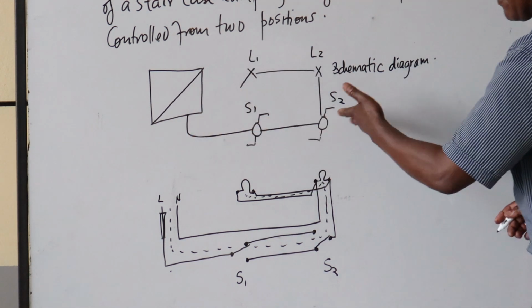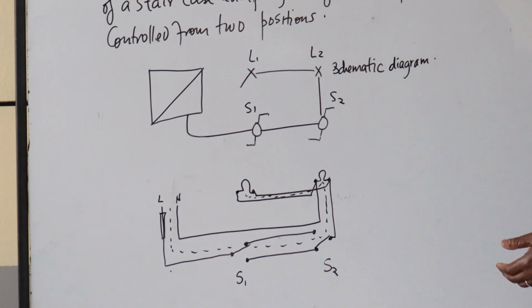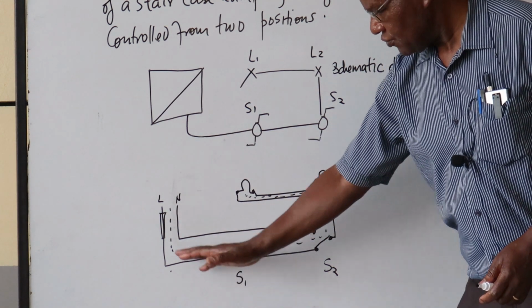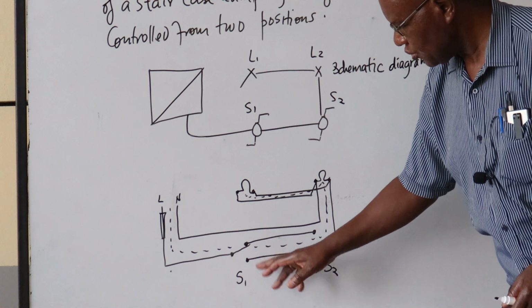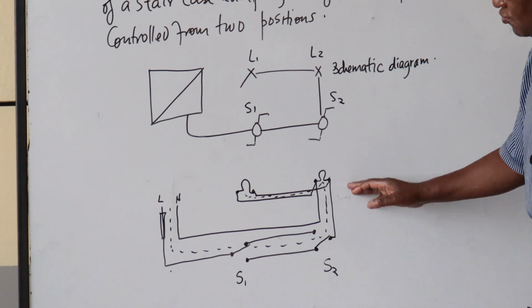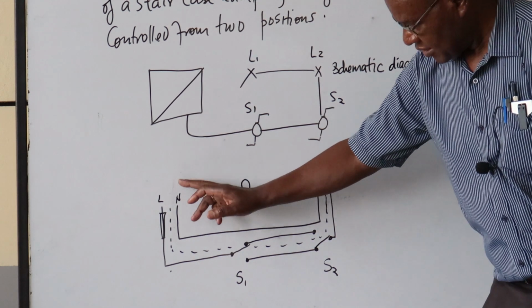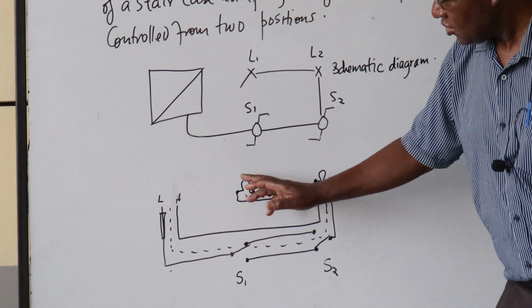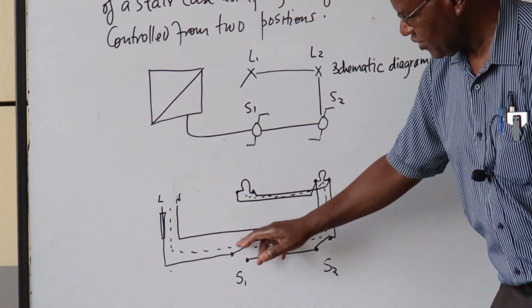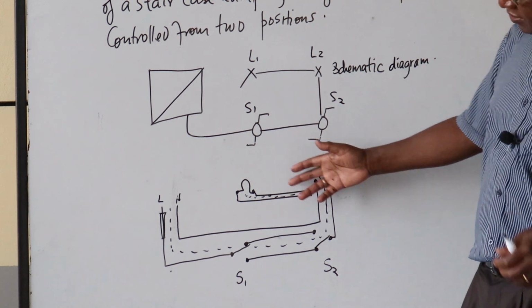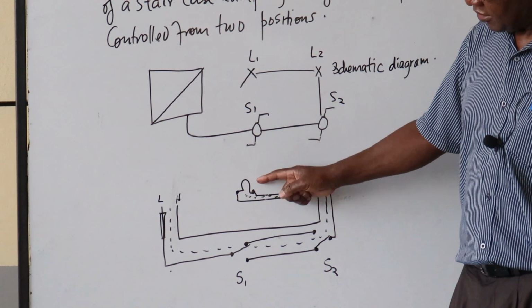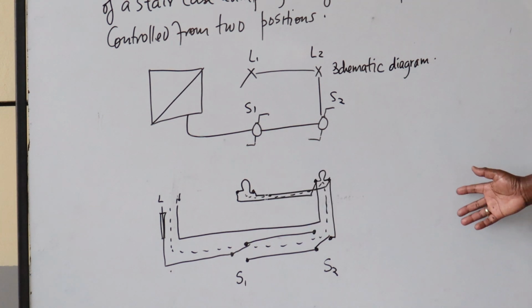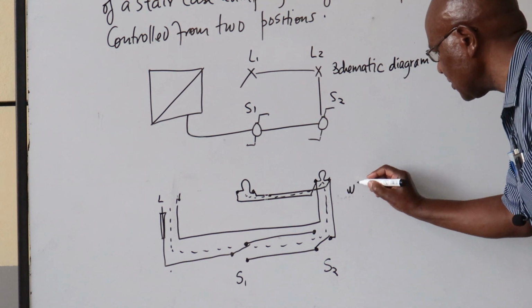Then the straight lines are our conductors, which run to connect to the various accessories. Then when it comes to the wiring, the live goes through a fuse, then to S1, a 2-way switch, then to the other switch, and then on to the lamps. Similarly, the IE tells us we also need the ECC, the earth continuity conductor, to be available at all those various points. The reasoning being, in future we may need to connect a circuit here. In our case, it may be a fluorescent lamp which needs the earthing. So the wiring diagram would look something like that.